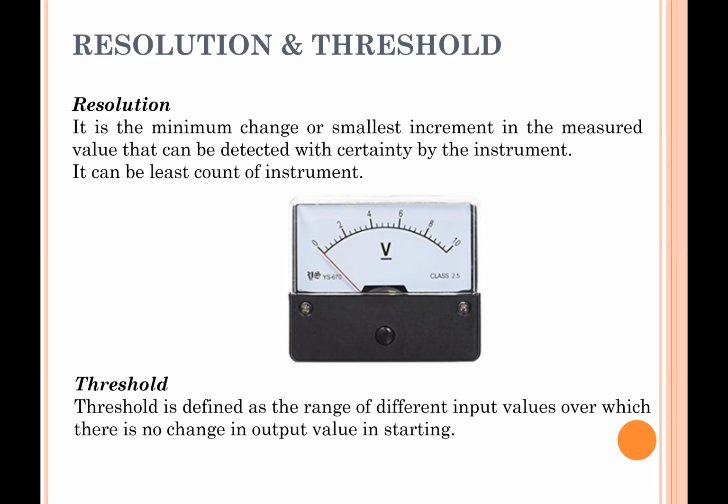Only then it starts working. If your motor की rating जो है वो 5 volts है और आप उसमें 2 volts की बैटरी लगाओगे, motor doesn't work. That means 5 volts is the threshold value जिसके बाद वो device active होगा. और जो भी accuracy, precision, resolution जो कुछ हम पढ़ रहे हैं उस रीडिंग के बाद वो फॉलो करना स्टार्ट करेगा. There is no reading below that scale.